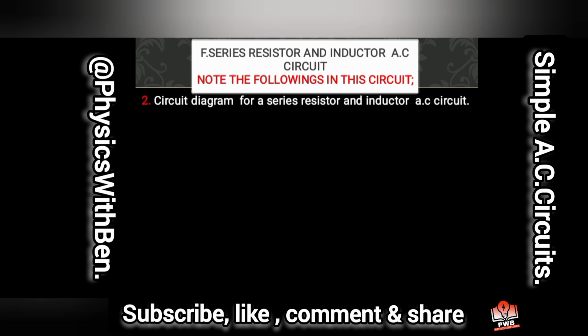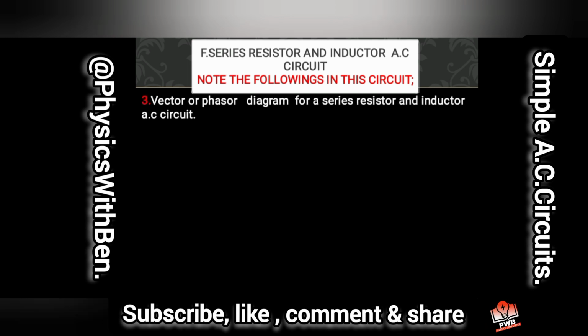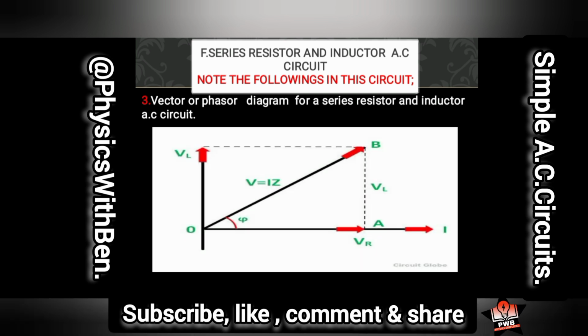Next up, examiners may ask you to draw the circuit diagram, and this is it, as I showed you earlier, no polarity. The phasor or vector diagram for a series resistor and inductor circuit, this is it here. This phasor diagram is very, very important. You can decide to use this phasor diagram to generate all the equations. I explained that in the video series.